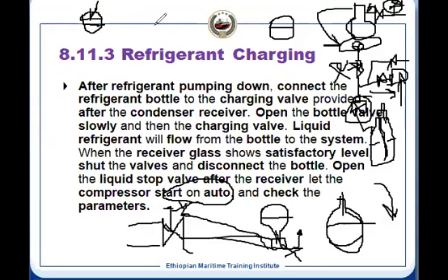So when you are running the system, for an example, when you are pumping down, it will be slightly higher than the midpoint. And when you are running the system, it will be around midpoint. It means definitely it has to be visible in the cycles. Design it such a way. So if after the pumping down it is slightly higher than the 50% midpoint, and when you start the system, even with all the three chambers, or two systems, all complete 100% capacity, that time also it will be within the sight glass. It will be maybe slightly half or slightly lower than the half, but it will be in the sight glass.